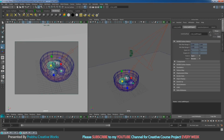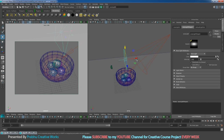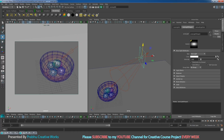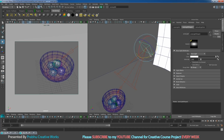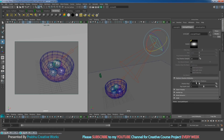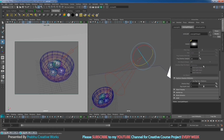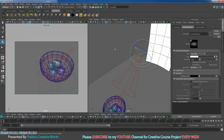So go to the rendering tab and choose area light, press R and scale it a little bit bigger. Press E and rotate in Y. Press W and move it exactly where the caustic light will be placed, like this. Now press E and rotate in X, so you angle it a little bit and rotate in Y. Now turn on Raytrace Shadow for this area light. I will give intensity 0.5. I want to check if it will be perfect or not.